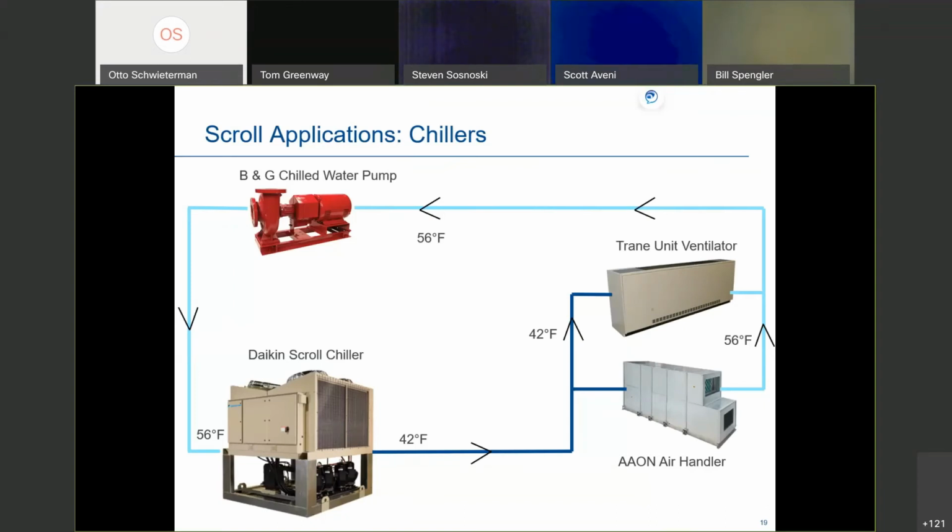So this type of system, chilled water systems, does a very good job at handling various loads throughout the building and throughout each space. These air handling units a lot of times will have a valve which varies how much water goes through the system itself. So you don't need to have 100% of the water that was designed to go to this chilled water system. You may be able to reduce that down to 50%, 30%, whatever that air handler unit can withstand, enough to still provide that 55-degree cooled air to the space.